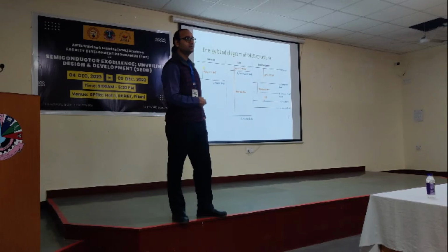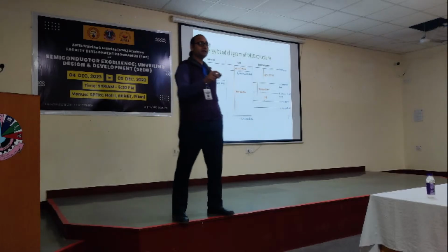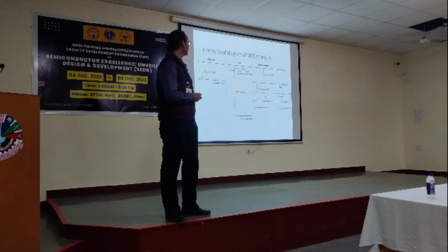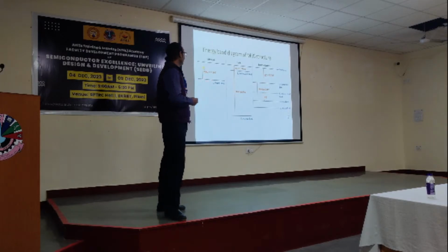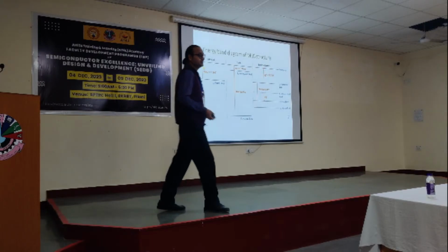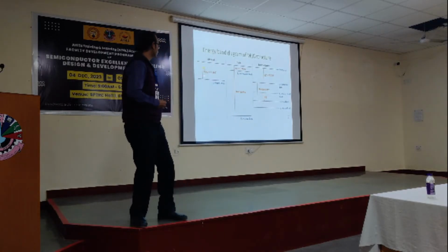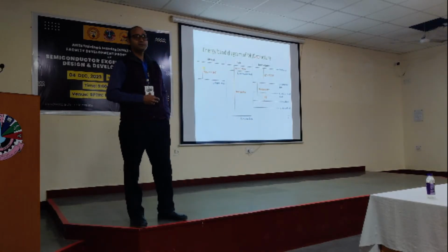So what needs to be done now? In case of the semiconductor, there will be some band bending. Can anybody tell me at this moment where the bands will bend in the semiconductor? And what is going to happen in this situation? The work function of the metal is smaller as compared to the work function of the semiconductor. What does this mean? What is the probability now? That means from the metal we can easily get an electron out, right?